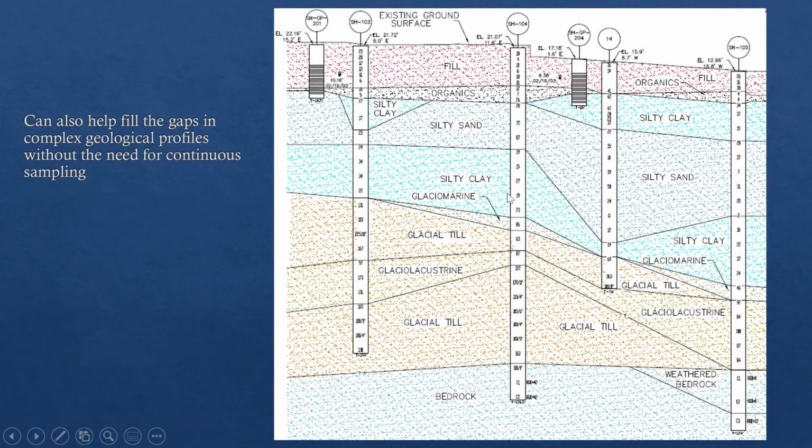This is from the same site. This is the overburden. So it can get very complicated. And again, if you don't have to do SPT everywhere, you can really use the MWD and do more boreholes and refine this stratigraphy.